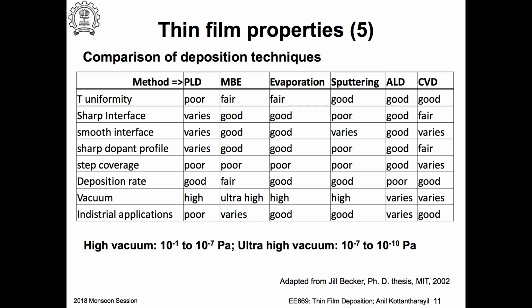What happens is that when you are talking about this kind of vacuum conditions, every molecule that comes out of the surface of the chamber matters, so this is not trivial. If anybody does thermal evaporation or electron beam evaporation, for a moment take your eyes off your mobile phone and look at the vacuum gauge.